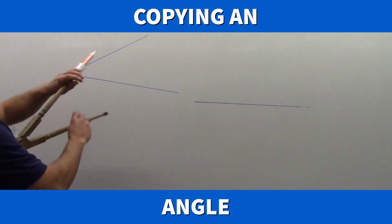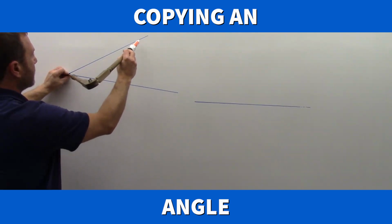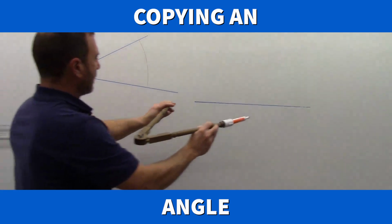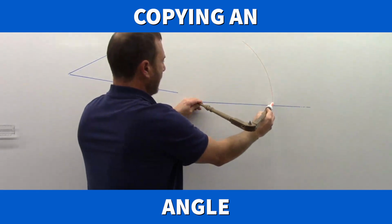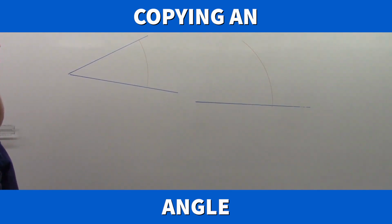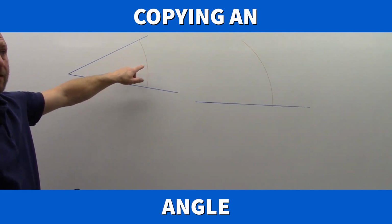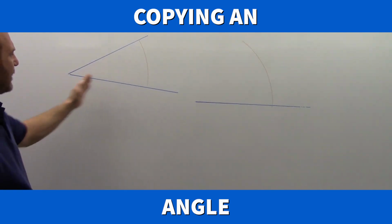Now again, I'm going to take my compass and set it to a reasonable distance and swing an arc. And since I'm set, I'm going to just swing that on my new baseline where I want the angle copied to. Now what we said earlier was the angle is in coordination with the arc. So whatever the radius is and corresponding angle, those will always be the same for the same radius and the same angle.